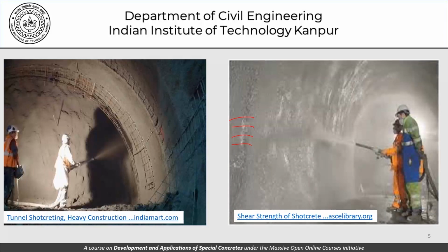What we should make sure when we are trying to do shotcreting in this layered manner is one thing about the joints. These joints should be such that the concrete across these two joints is not separated. It's just the normal consideration for cold joints. We don't want these joints to become cold joints. And secondly, we should make sure that this entire mass of concrete does not fall off, because we should remember that shotcreting as an operation at times is being carried out against gravity.